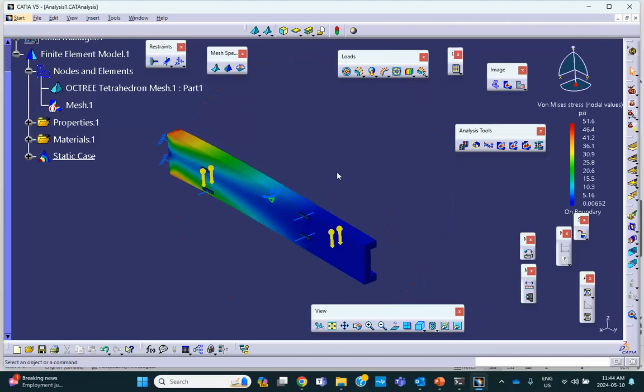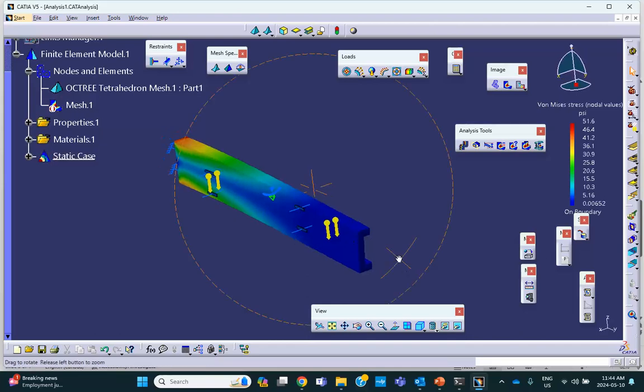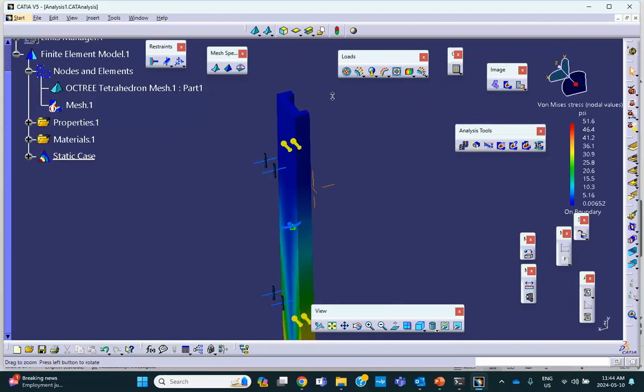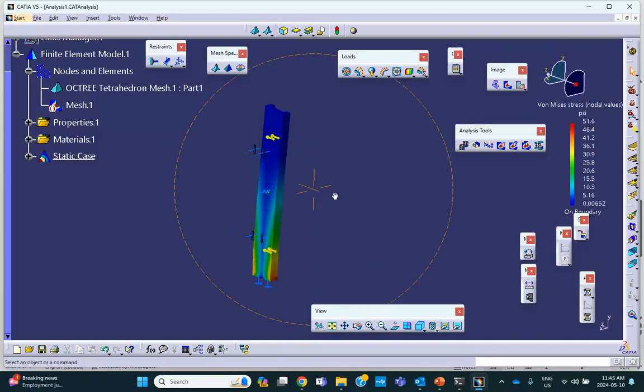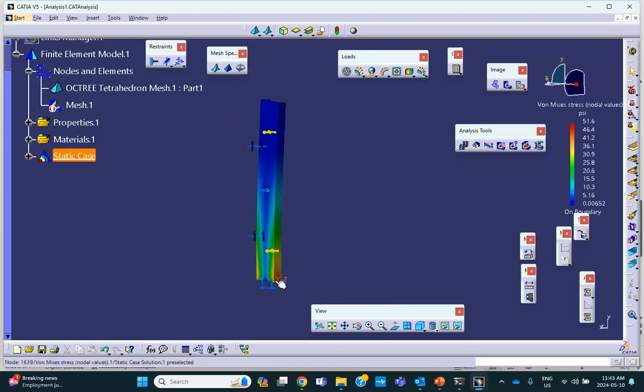Now, just keep in mind that if this was not under gravity, suppose this was the antenna on my car, as I mentioned in the class or in the lab, and the car was accelerating, then it's not gravity making this bend, it's the acceleration of the car that makes this thing bend. So you know to apply acceleration. You know the pressure, you know the force, and now you know the acceleration. Okay, good. So that takes care of the first problem.